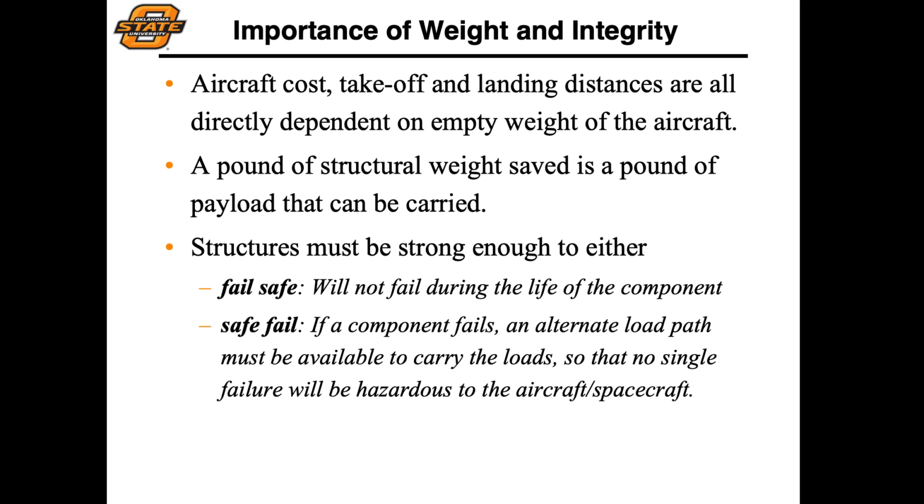And we'll talk about this in another lecture specifically discussing weight prediction and considerations. But you can also think about this from the standpoint of how much payload that aircraft is going to be able to carry. If you can save a pound of structural weight while still maintaining the same load carrying capability of the aircraft, that means that you can then carry a pound of payload instead, or perhaps a pound of fuel if you have the volume to carry that fuel as well.